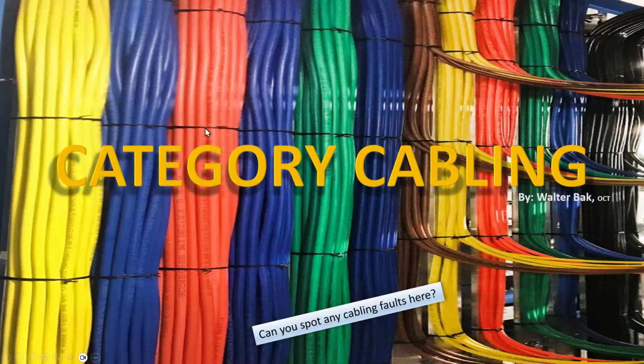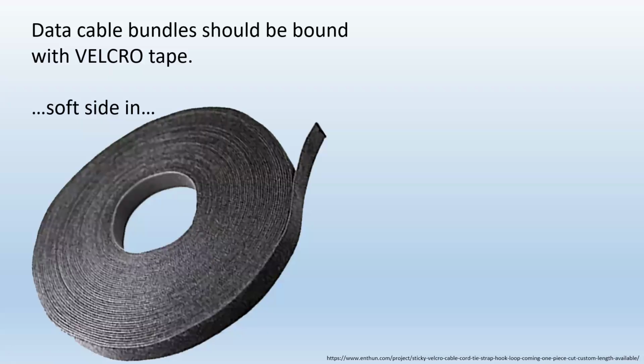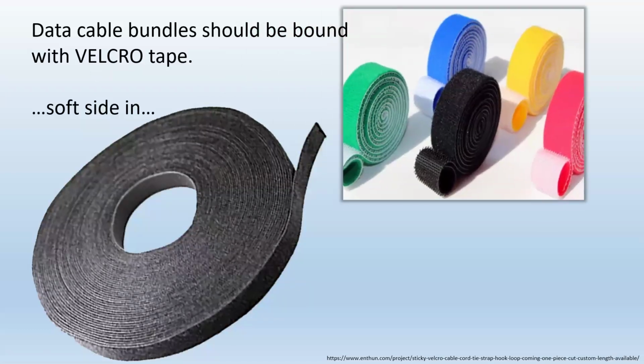So what are we supposed to use? We're supposed to use Velcro. Okay? Data cable bundles should be bound with Velcro tape, and to make sure that things are nice and beautiful, soft side in. So the soft side of the Velcro is making contact with the cables. Here are some examples